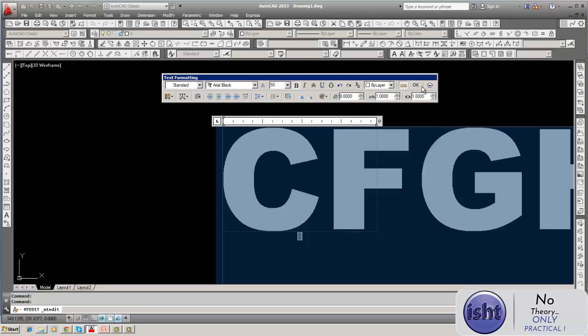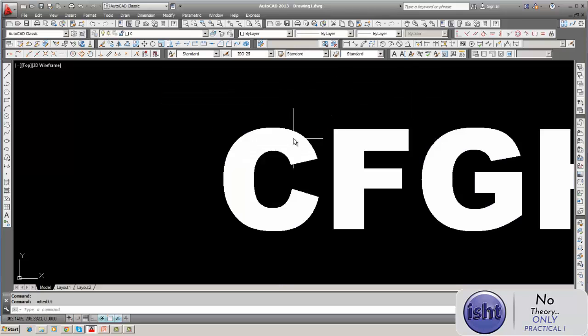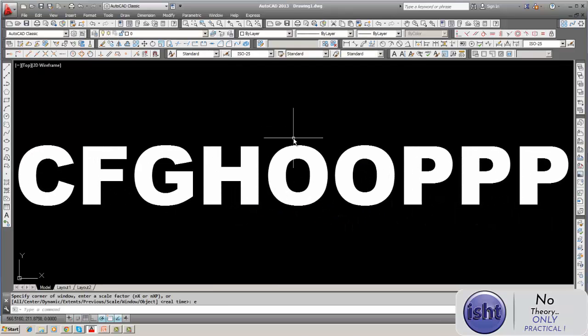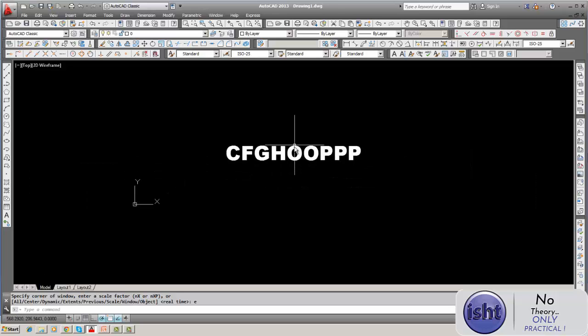So this is such a big letter. If you type this, on the paper the drawing will be reduced to 1/10, that's 200 mm and 100 mm, and this letter 50 mm is reduced to 5 mm. So this is also reduced, no? That means the letter height should be multiplied by the reciprocal of the scale factor.